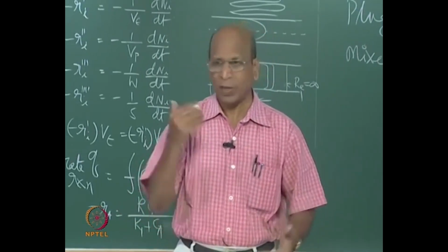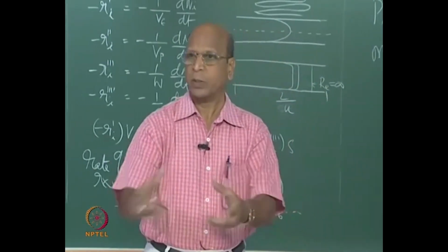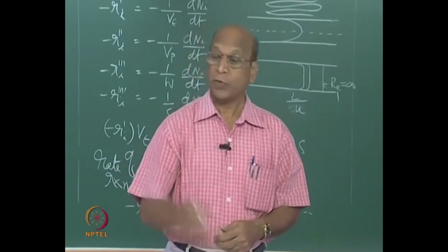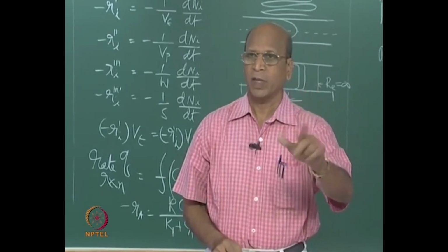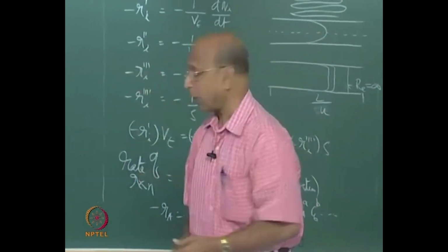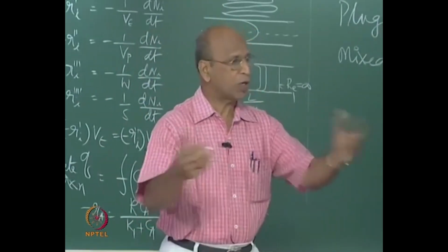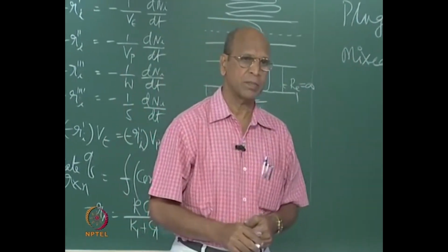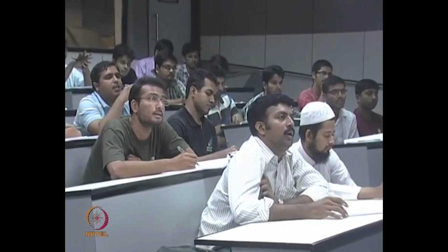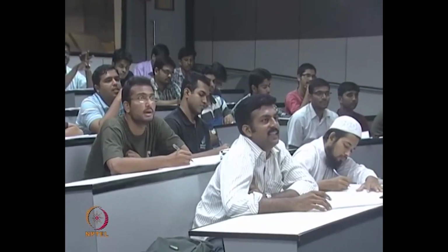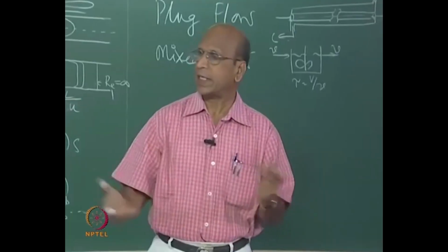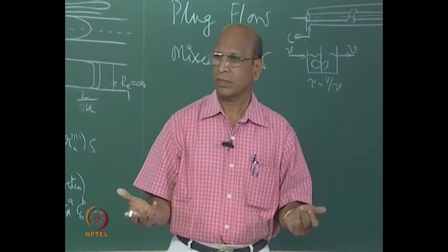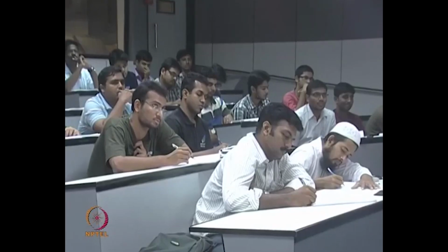So, that is the reason why even for gas phase I have to go sometimes for mixed flow reactors if it is continuous, if it is highly exothermic. So, these are the main two criteria for choosing between plug flow reactor and mixed flow reactor. Now, can you repeat, when do you choose mixed flow reactor? When temperature control is required and when large residence times are needed, that is all. Okay. Any other criteria? There is no other criteria except this.